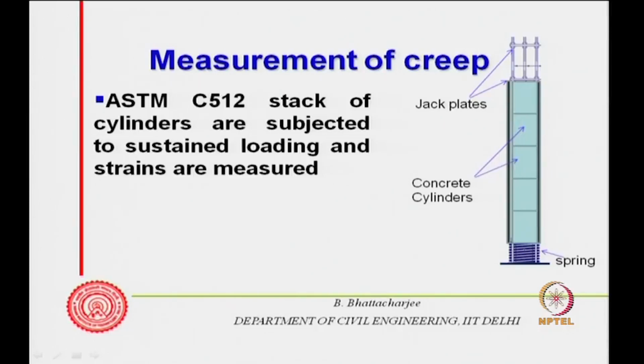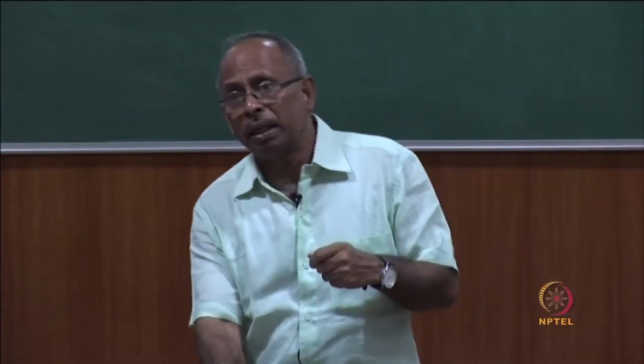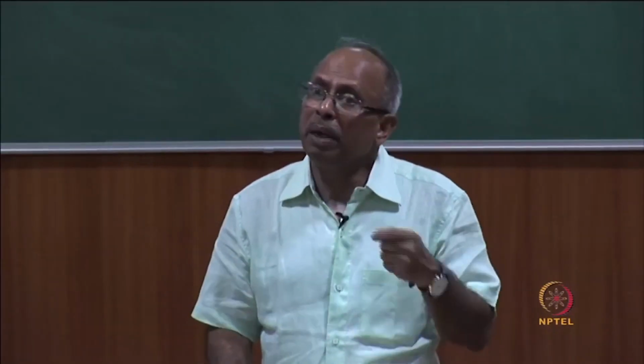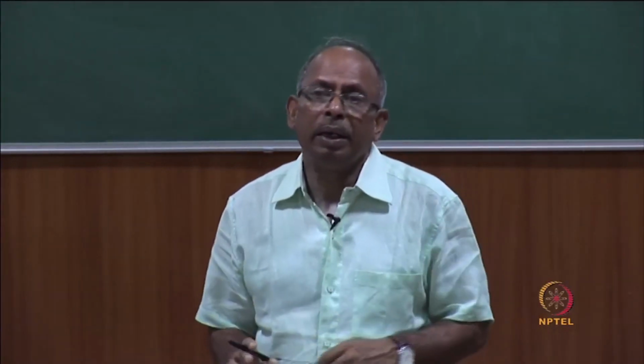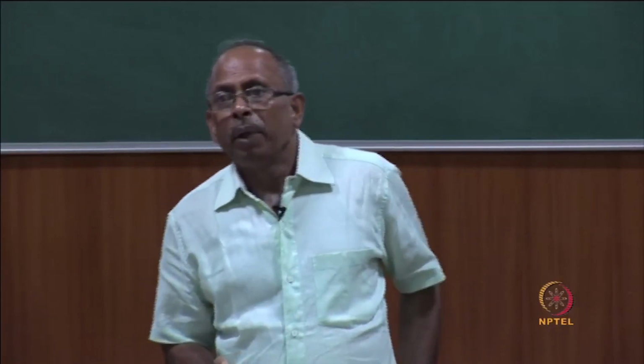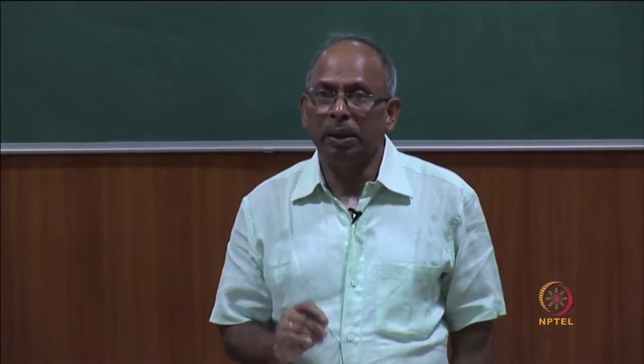Now, what do you measure? You put strain gauges; varieties of gauges have actually been suggested in the central portion. Strain gauges or all kinds of gauges are possible. You can insert them, put them on the surface, or even embed them. All possibilities are given in the code, and that is how creep is measured.